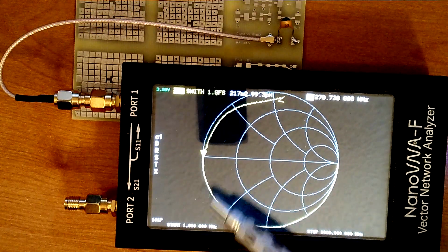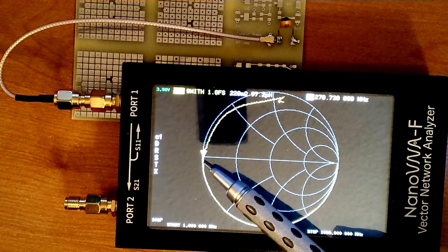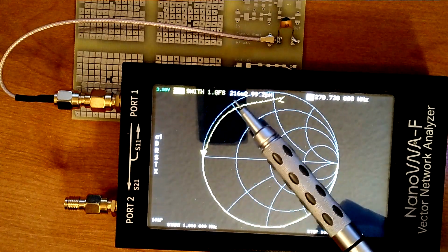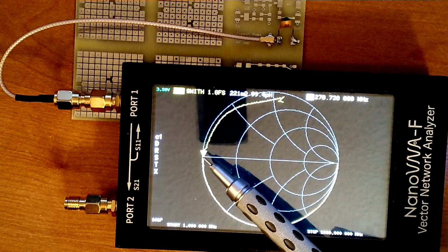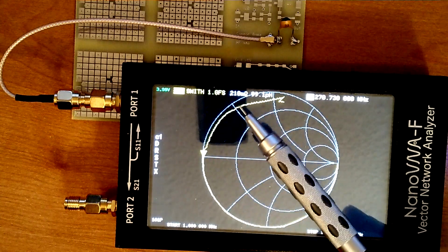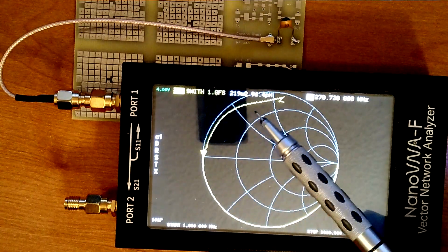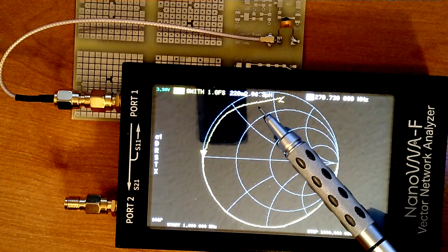All right, so over here, I've now moved into the picohenry zone, so the thing is starting to become inductive, but it's essentially nothing. It's just resistive, but it's about 0.2 ohms. Give or take a little bit. We're not quite sure how accurate the network analyzer is. They tend to be pretty decent, so we're somewhere between 100 milliohms, 0.1 ohms, and 300 milliohms, 0.3 ohms. It says 0.2, so we'll call it that. Notice, though, that as we go higher in frequency, it would move up into here, we would have much more inductance and more resistance as well.